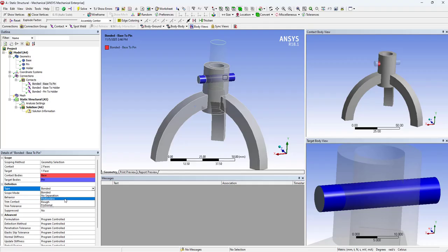If I move to the frictionless support, as the name suggests, the two surfaces are in contact with each other. However, there is no frictional coefficient between them. So the two surfaces are considered as frictionless. This is a non-linear kind of support, as it also allows a small separation between two surfaces. Like it is possible that the two surfaces are not in contact initially, and when we apply the force, there exists a normal force, and those two surfaces start to be in contact with each other.